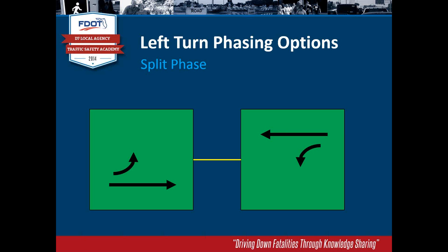So again, it's a safety concern, making sure you have the sight distance or the geometry necessary to operate the left turns, that would make you choose split phase or possibly lead lag.